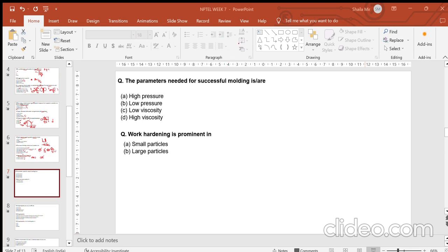H by D ratio is a characteristic of your particle. For example, if you have a sphere, this will have a different H by D ratio, or if you have an oval, that will have a different H by D ratio. If you have a cylinder, you have a different H by D ratio. It's based on particle morphologies. These will change, and the compaction pressure will also be affected. So you have to say, if you have a high compaction pressure, the H by D ratio will increase, decrease, or remain insufficient.